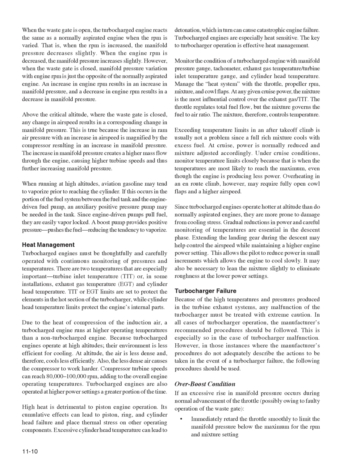Turbocharged engines are also operated at higher power settings a greater portion of the time. High heat is detrimental to piston engine operation. Its cumulative effects can lead to piston, ring, and cylinder head failure and place thermal stress on other operating components. Excessive cylinder head temperature can lead to detonation, which in turn can cause catastrophic engine failure. Turbocharged engines are especially heat sensitive. The key to turbocharger operation is effective heat management.